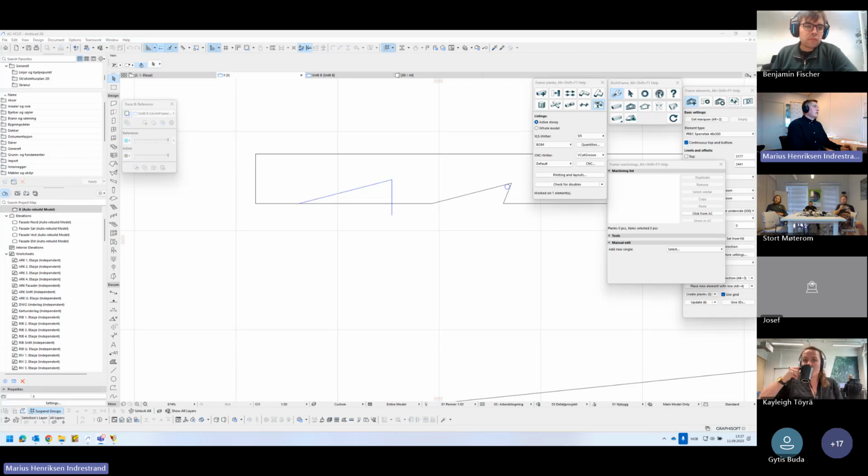As I showed in the example, when using VCuts, our Hundegger tries to use the revolver drill bit, the big 98 millimeter one, and if using that, you can get some splinter if it's not really sharp. But it will be the same with the saw blade, of course. If you have a dull saw, you will get splintering.